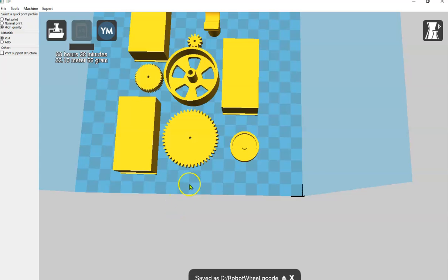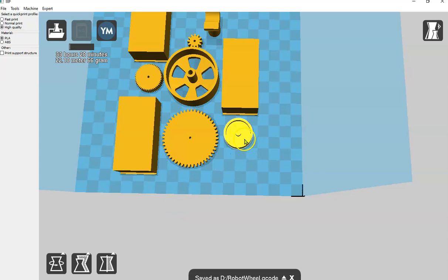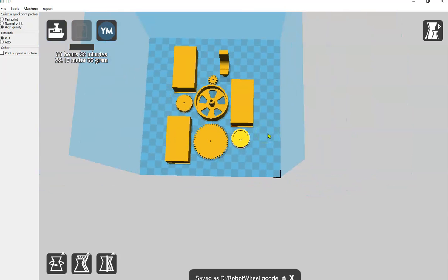For placement on the bed, it's okay to put these really close to each other. It's impossible for you to push them too close to each other. The software knows how to fix that, so don't worry about that. Do worry about getting it too close to the edge of the build plate. Try to leave 2 squares between the edge of the build plate and your part.